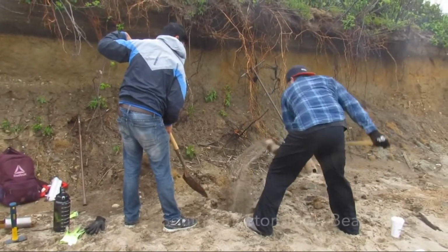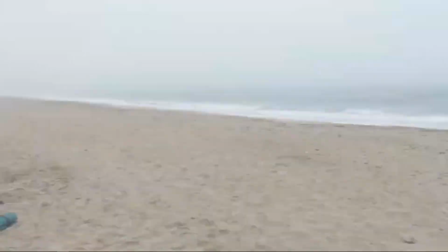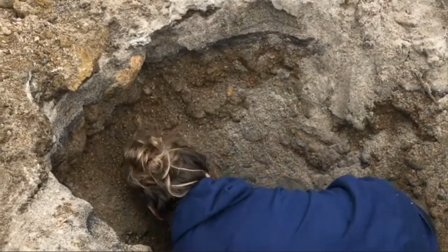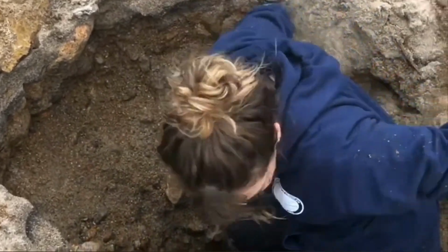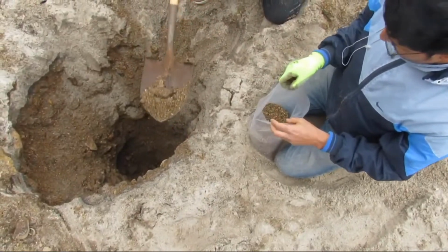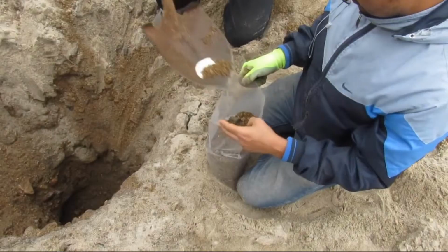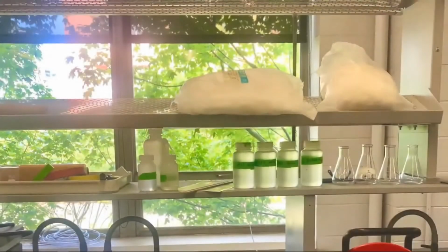Geology of coastal aquifers is not homogeneous. Taking samples to bring to the lab and measure its hydrogeological characteristics allow us to correct what we saw from the ERT data and make assumptions about lithology. Here, we are taking samples from several locations along the South Kingstown town beach where we did an ERT survey. ERT surveys give us bulk resistivity. Taking samples and finding aquifer properties can correct our image to fluid resistivity.